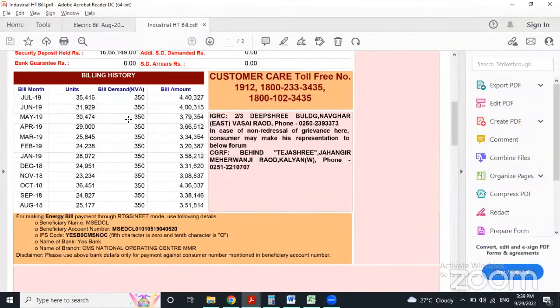ask him for 12 months of bills, but take the average over the year. That will be a more optimized design. Don't take a single bill and do the calculation based on that, because the value might differ from the average. Just as with the solar power plant, where generation is also averaged over the year, the consumption from the grid should also be averaged over the year.